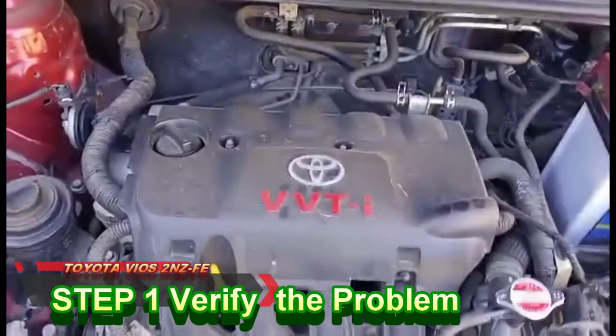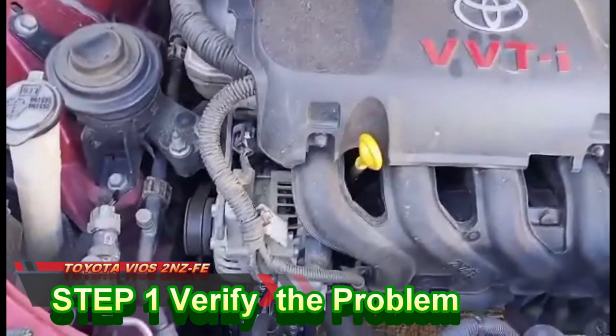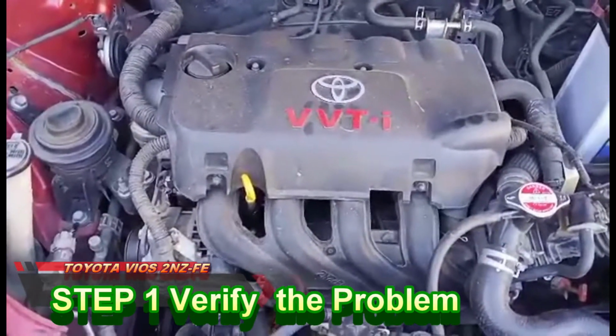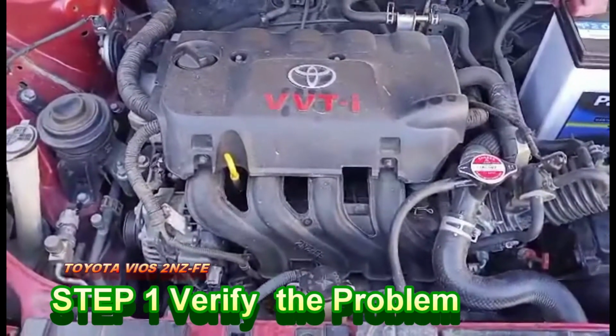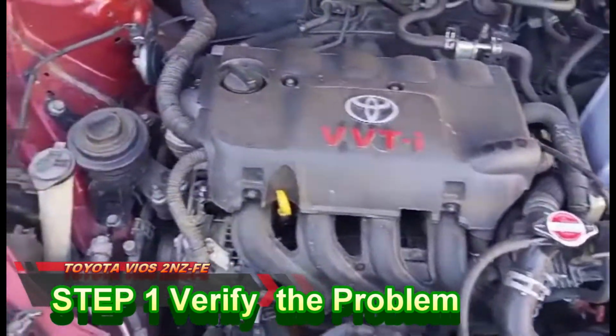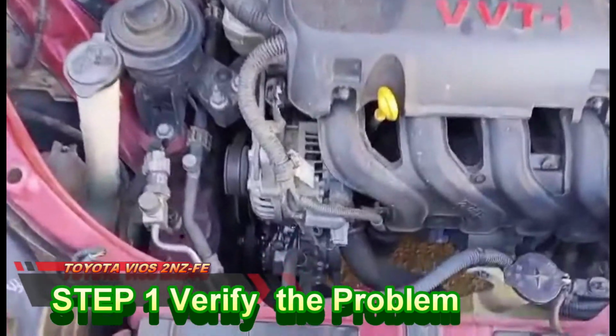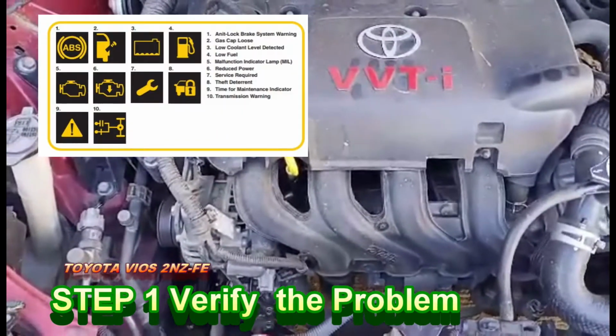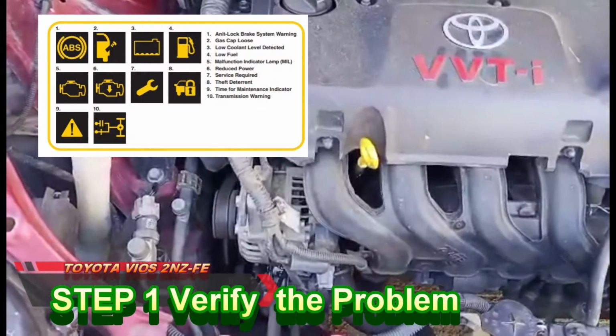Step 1. Verify the problem or concern. Before a minute is spent on diagnosis, be certain that a problem exists. If the problem cannot be verified, it cannot be solved or tested to verify that the repair was complete. See Figure 1-2. The driver of the vehicle knows much about the vehicle and how it is driven.